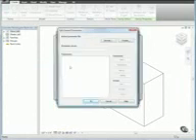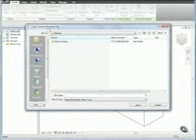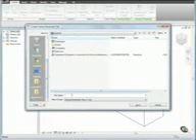In the Parameter Properties dialog, click Shared Parameter and then click Select. In the Revit dialog, click Yes to specify a shared parameter file. In the Edit Shared Parameters dialog, click Create. In the Create Shared Parameter File dialog, specify a location for the file and name it Project Shared Parameters and click Save.